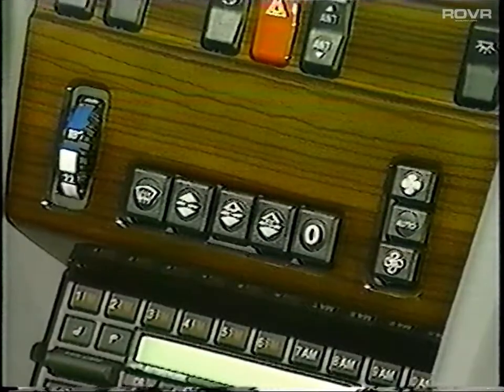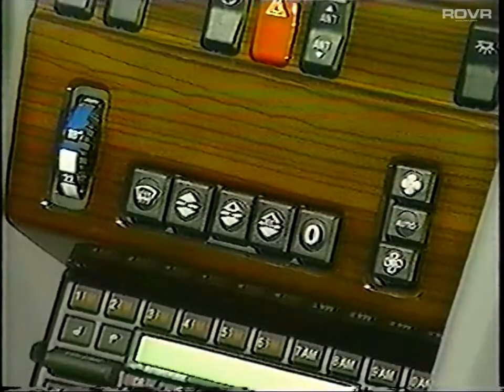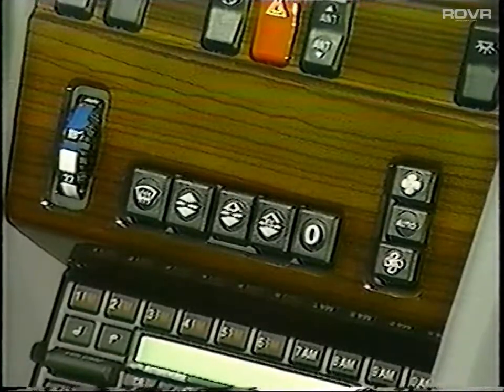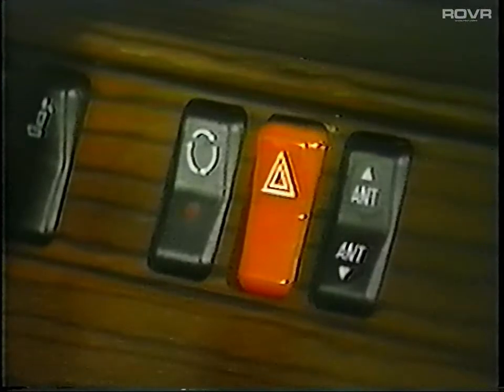And a final point regarding the climate control test. You will notice that during the impulse readout, the LED in the fresh recirculated air switch will blink. The blinking is of no significance for test purposes.